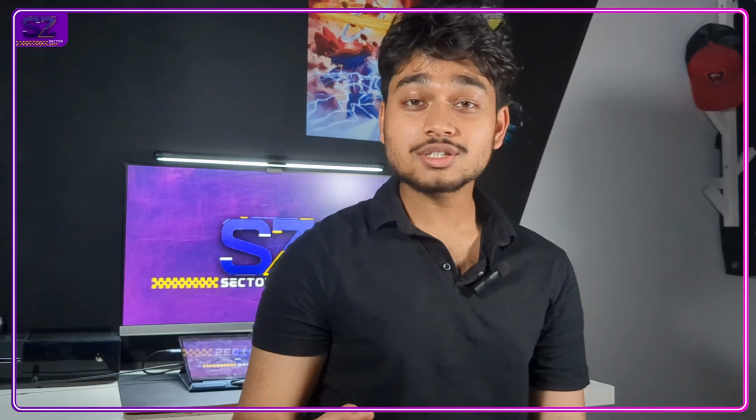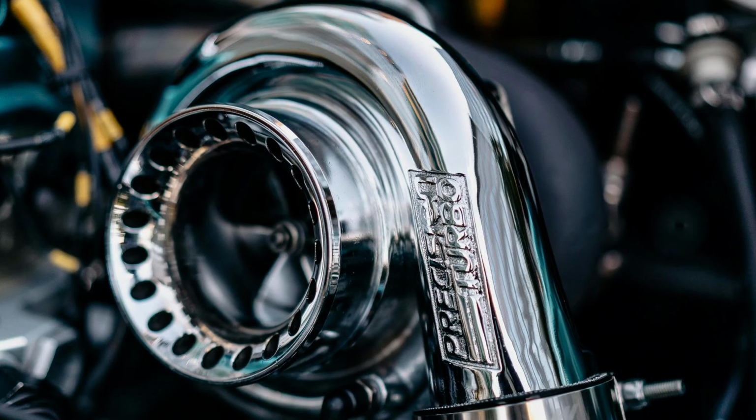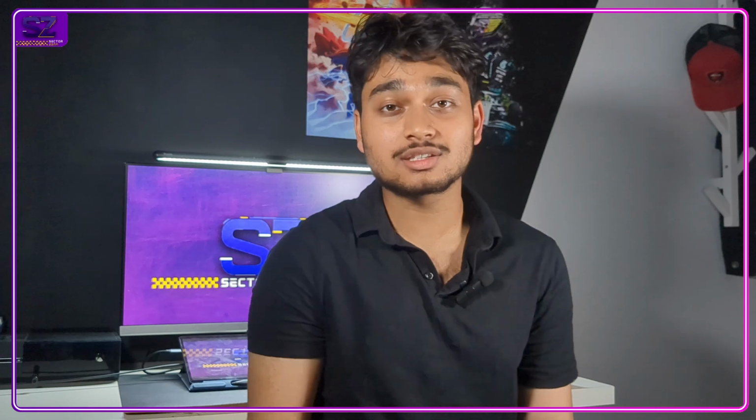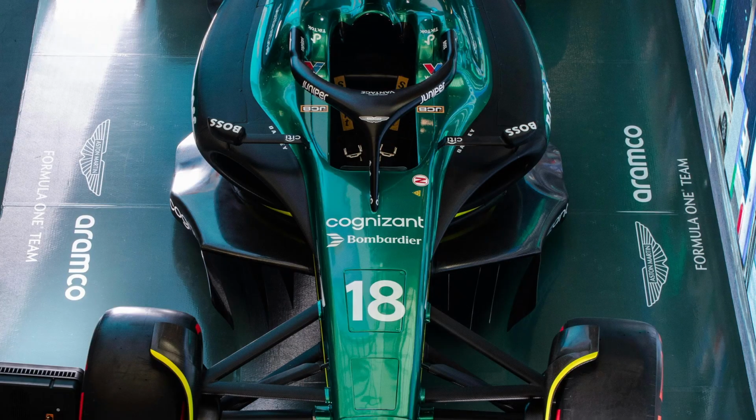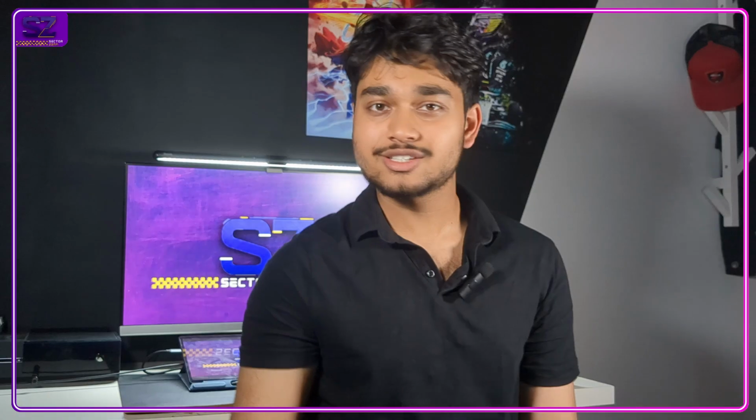That means that combustion is less efficient. But thanks to turbocharging, F1 engines can compensate. The turbo simply spins faster to compress more air. But because it's spinning faster, it generates more heat, which brings back the cooling issue. To deal with it, engineers might open up more bodywork on the car than normal, enlarge cooling inlets, or add gurney flaps in to aid with extraction. But each of these additions add drag, so it is a balance.